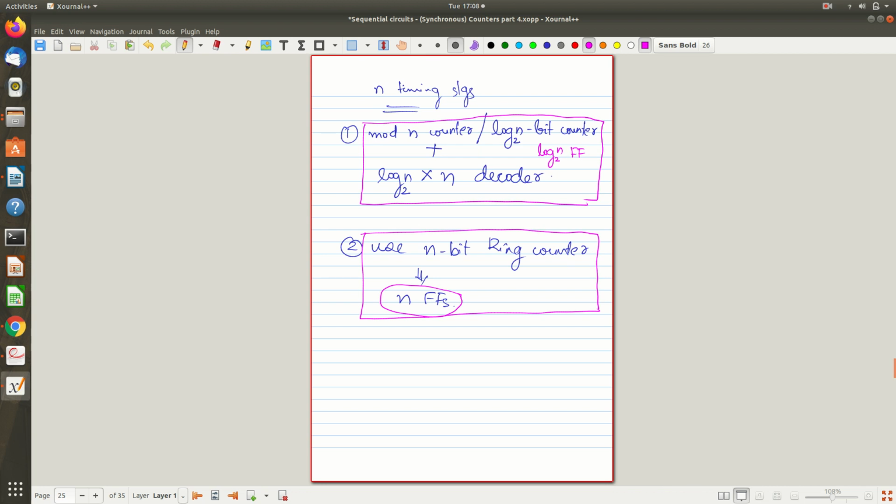For example, if it is a 4/16 decoder, 4 inputs will come, like I0, I1, I2, I3, so that the first output of this decoder is I0 taken as it is and the other bits taken as complements, and you will use an AND gate for implementing this in the background. It has already taken time, so explaining the AND gate specification would take more time. So I'm not explaining that at this point.